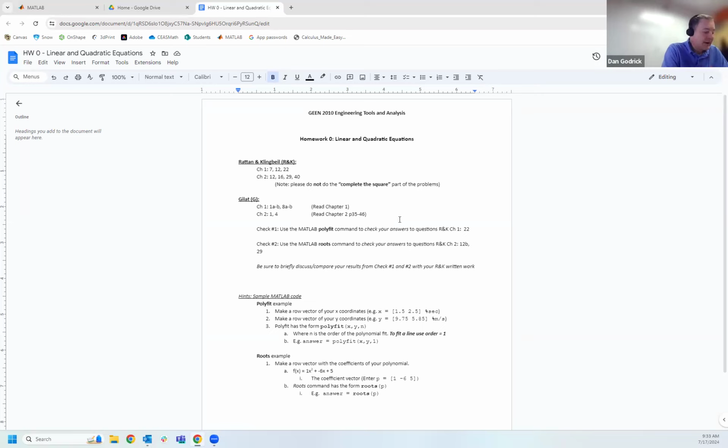And now we look at the data. Again, 2 points, Vs and I. Vs is on the side where it's isolated. That's our Y. So we have 2 points, and each one has a Y, 2.0 and 6. Then we look at the right and it says I, and it's 0.035 and 0.135. That's our X. So again, use that tool, solve for M, solve for the intercept, and in this case, M is Rd and V on is our intercept.